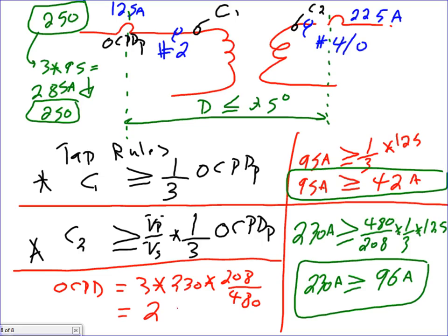$299. 299 amp, and then you're going to go down to where? Because it's not standard, down to 250. 250 amp. So the same, surprise, surprise, came up with the same answer, 250. So I could have, had I come with 200 here, then 200 rules. Then that overcurrent device cannot be more than 200. Long story short, guys, this will give you a way of oversizing your secondary because of inrush and still meet the code. Still meet the code.